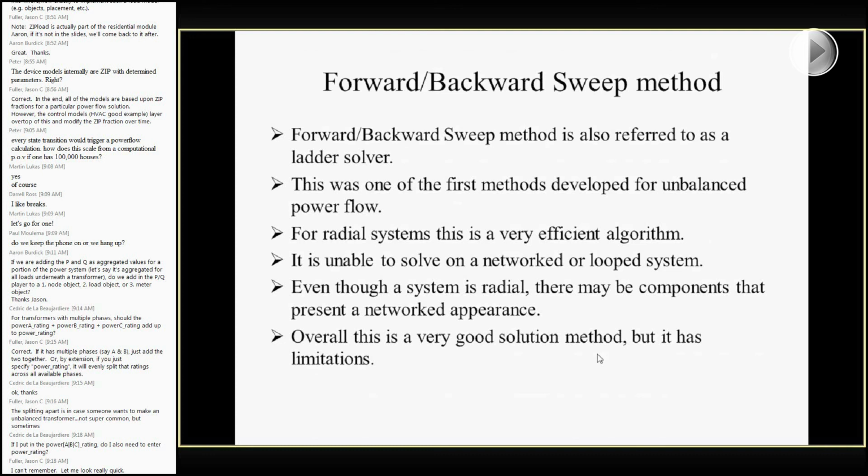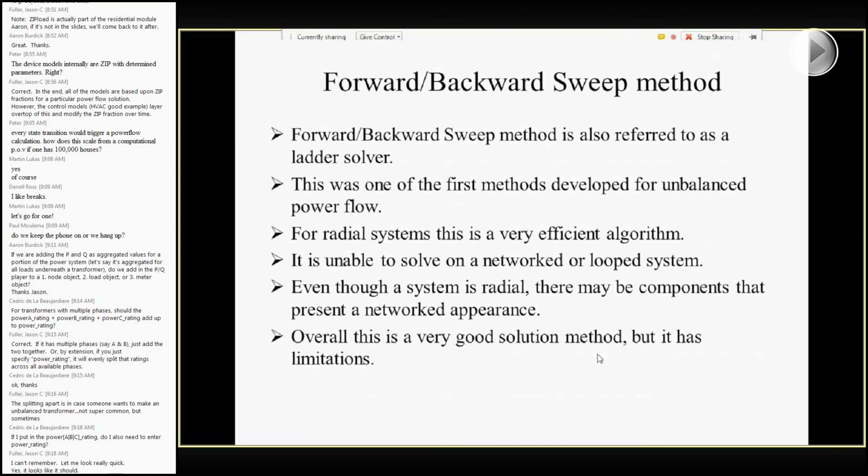As I mentioned, it's based on simple circuit analysis, which is nice in that it's an elegant, simple solution, and easy to follow. As a result, it's a fairly efficient algorithm. It does take a little while to converge if you've had a very large change on your system, but since it solves fairly quickly, that isn't much of an issue. It'll iterate a lot more times, but you'll get to the solution overall a little bit faster.